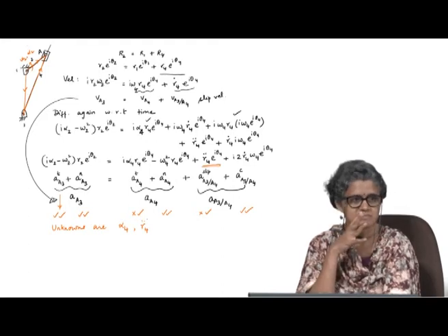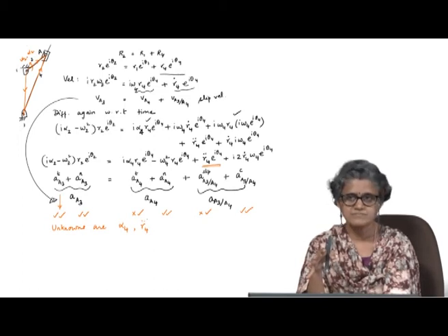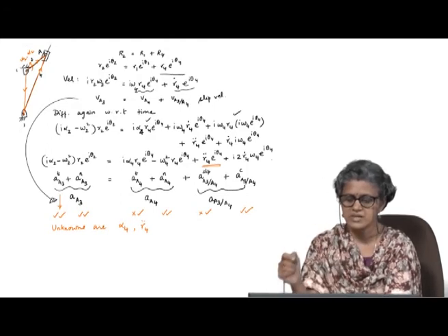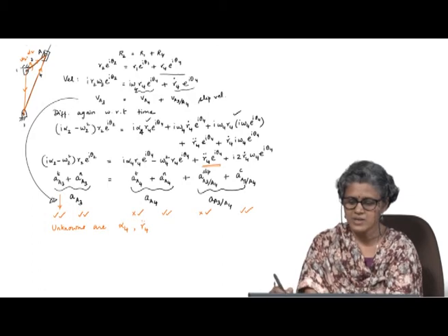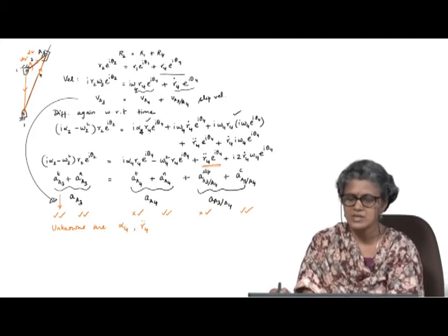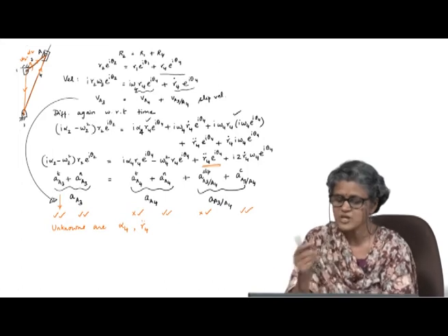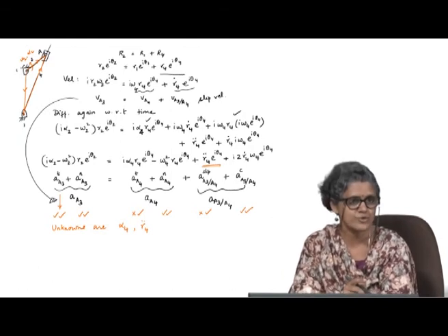Any questions on this? You will be comfortable solving this graphically? Okay. What is the direction of the Coriolis acceleration? It will depend on the direction of the slip velocity and omega 4. See, R4 dot e power i theta 4 is your slip velocity vector. So, the slip velocity vector will be rotated 90 degrees in the direction of omega 4.